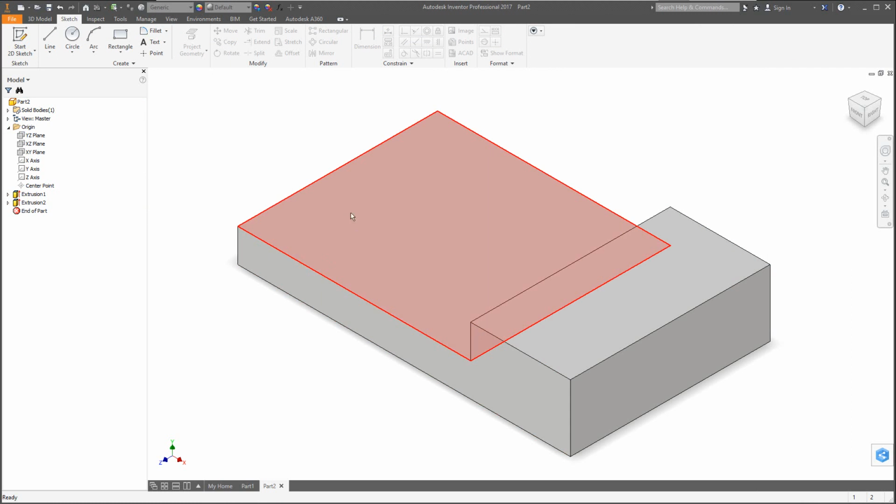Okay, now let's try and put a cut hole in here. So go ahead and select this face. Now when this pops up, could be a very useful thing. It's like a filter that enables you, wherever your pointer is, it will give you a selection of options that are close by. So it can be useful. I'll admit sometimes it could be an annoyance too, if you don't know what you're doing. But go ahead and select this face. And remember there's the 3 options again, and we just want the create sketch, which is on the right.